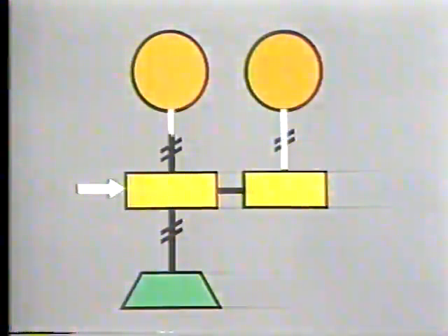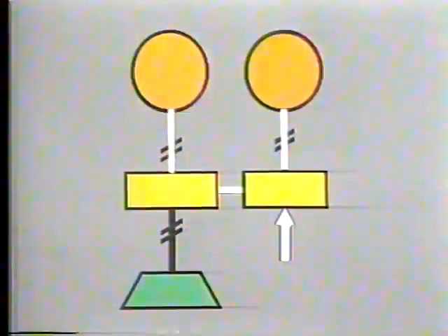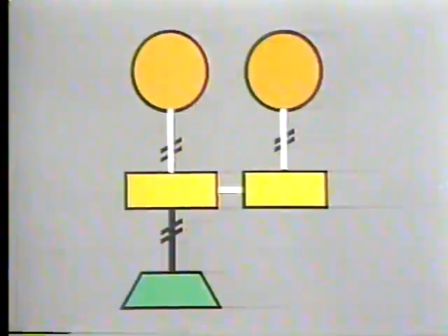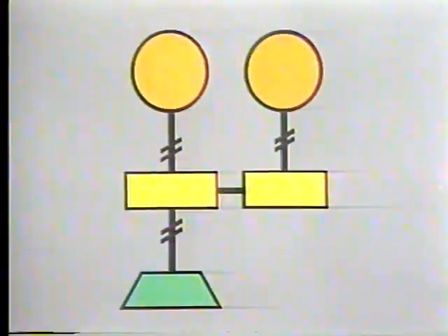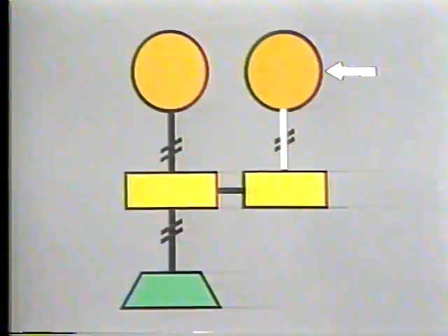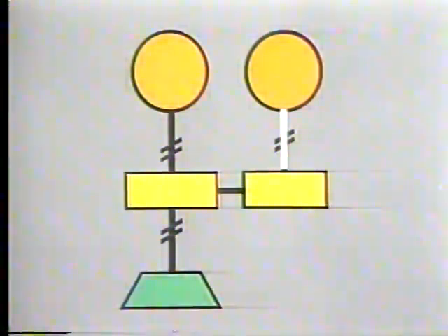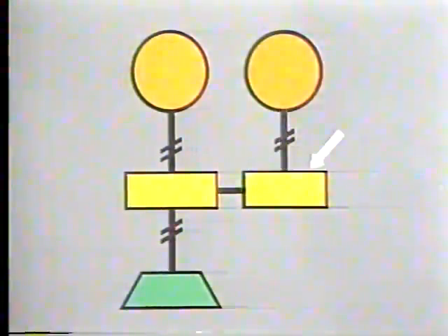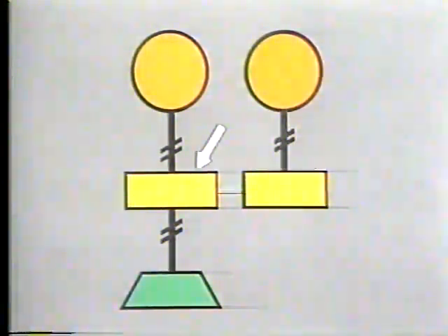Although this controller receives two inputs, just as the ratio controller did, one of these inputs comes from another controller. And this is the major difference between a ratio and a cascade arrangement. In most cases, when a controller receives an input from another controller, the system is cascade. In this particular arrangement, this controller receives an input from a measuring device. The controller compares that input to an established set point and produces an output signal that represents the difference between its input signal and set point. The output from this controller is sent to this controller. This input is the set point in this controller.